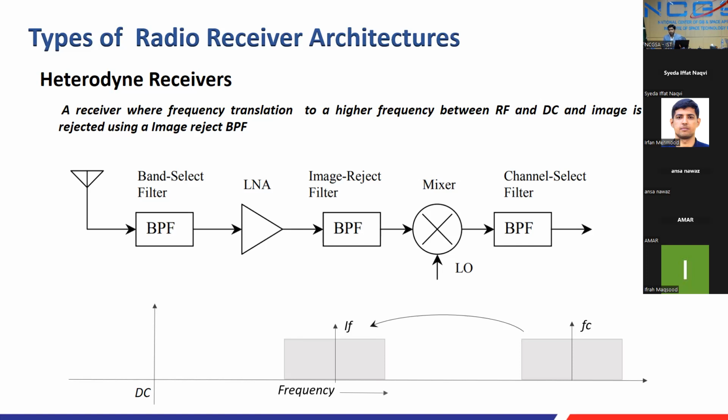What is the practical aspect of that? Practically, as you move towards lower frequencies, higher Q filters may be larger in size. Then you won't find assembly components for that. You will have to accommodate maybe a bigger size LC filter, or go through different trade-offs based on which topology you decide, which band pass filter, which frequency plan. So the main difference between heterodyne and homodyne is that in heterodyne you don't go near DC to avoid the DC loss, but it has its own trade-off.